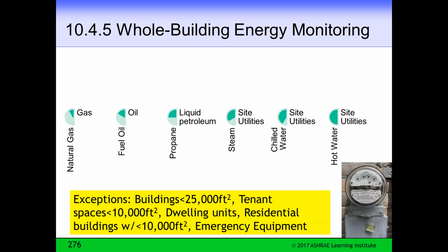All right, whole building energy monitoring. Now this is back to not the sub-meters, this is the real meters. So we've had a requirement for some time, I think a 2013 requirement, that you had to have a whole building electric meter, and it had to be a 15-minute meter, so we were monitoring the whole building electric use.